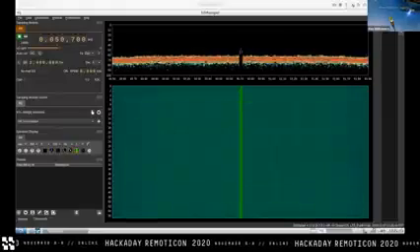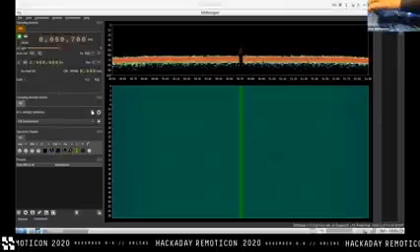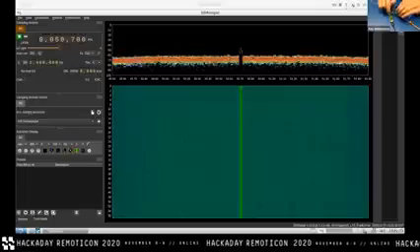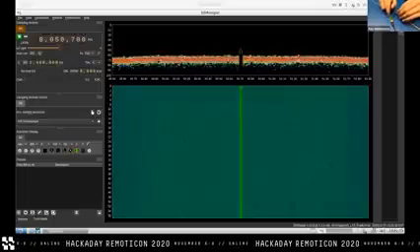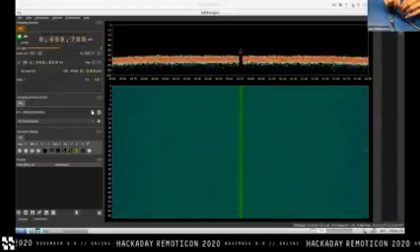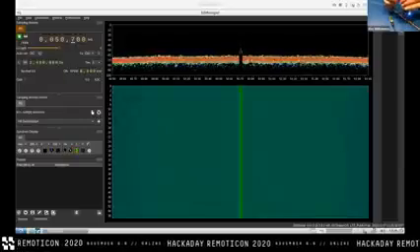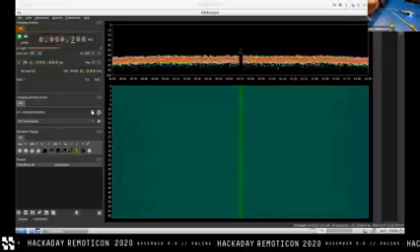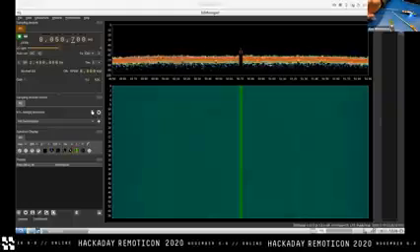Somewhere else on this board has that same 50 megahertz signal on it, and you should be able to use this same probe to find it. Because keep in mind, even though there's no load attached to any of these pins, there is a capacitance between the pin and air, and between the pin and its own ground plane and all the rest of it. So we are loading a very, very small value capacitor, or rather piping into a very small value capacitor, a relatively high frequency signal. You should be able to measure a current on some trace even out to just the